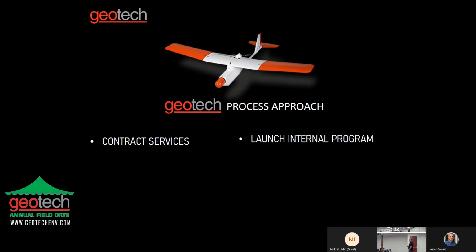That's a good question. So accuracy is going to be based on ground control, and the more ground control we add, the higher accuracy we're going to achieve. We find that high accuracy is not always really required. It's going to give you the volume, but it's not going to be highly accurate without ground control. If you have permanent markers on site that can be used for ground control in post-process, then as that digging hole is taking shape, they're going to get really accurate.